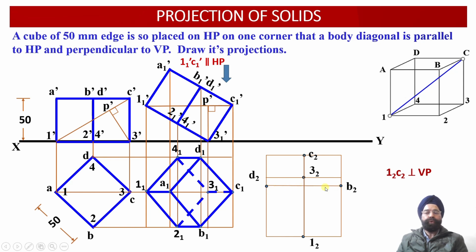Once we move to these two endpoints over here, another couple of points have been located in this vertical rectangle. Now again you can see over here, from this point we measure this distance, from this point we measure this distance, and again we draw a perpendicular projector line, and again on the boundary 2,2 and 4,2 will be located.